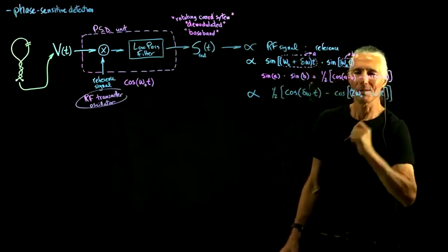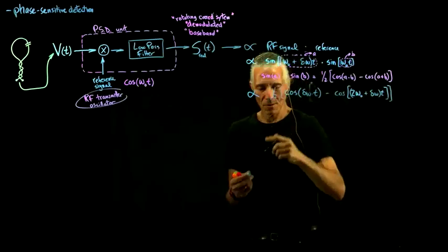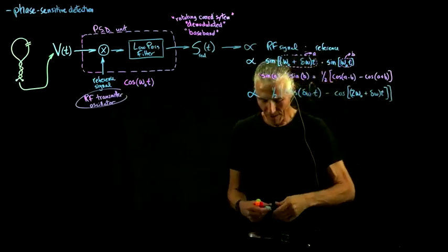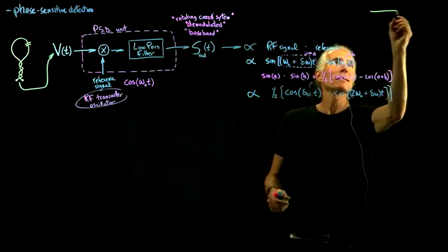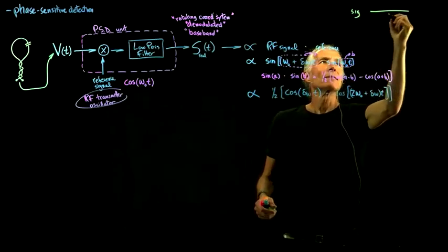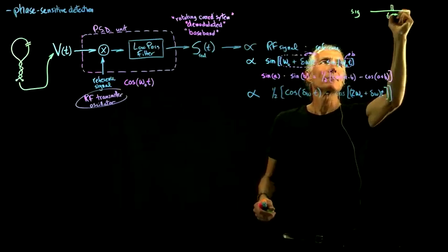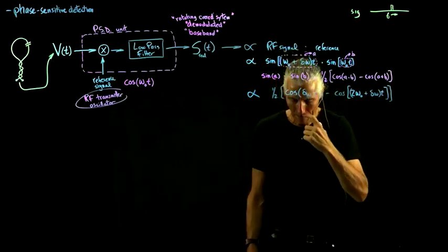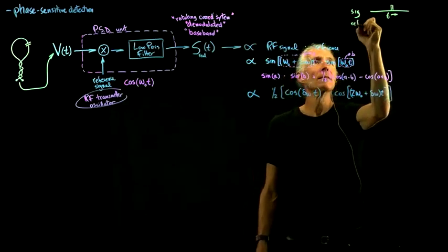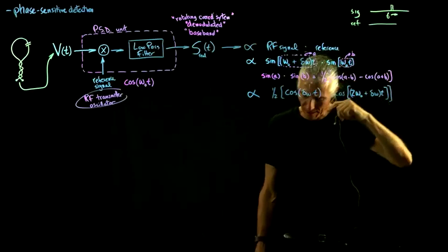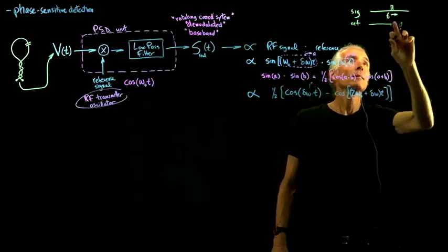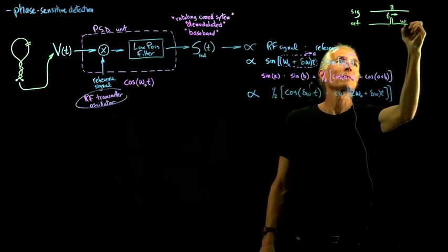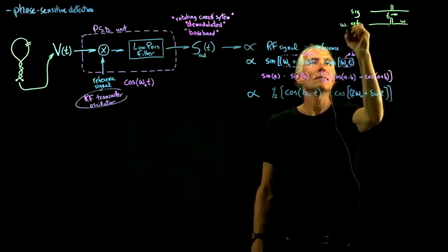And with another, there we go. So how can we, if we just draw that out in frequency, what does it look like? If we have a signal, here's our signal, and this is frequency going in this direction. It's a pretty high signal, 123.01 megahertz. And then we've got a reference, and the reference doesn't have to be exactly the same as the signal. Let's make it just a little bit lower than the signal. So this is our omega 0 reference.